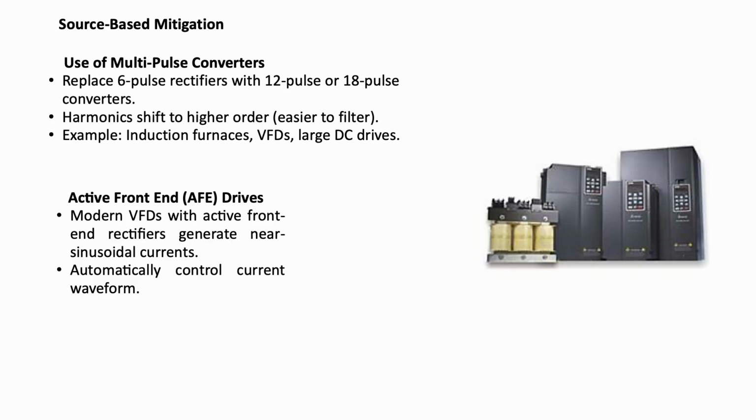These rectifiers draw almost sinusoidal current from the supply and automatically maintain near unity power factor. AFE drives continuously monitor and shape the input current to eliminate harmonics at the source level. Although they are costlier, they provide superior performance and are ideal for sensitive or high efficiency installations.